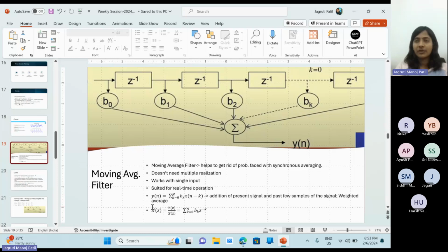So this is how, for each and every system, when you calibrate it, you find its response function. First of all, you find the point spread function, and that point spread function is defined by the impulse response. So this impulse response tells you what the system's resolution is, or how much you can actually differentiate between two different periods of time, or at a particular location, between two scatterers.